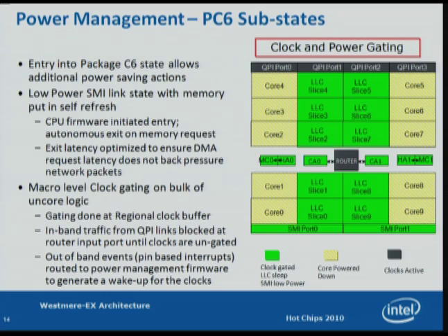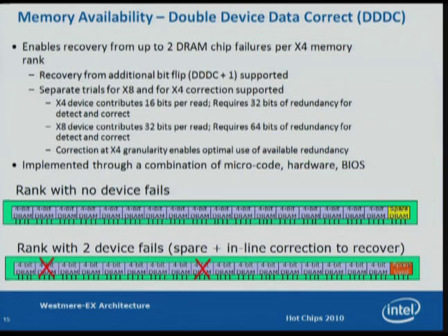There are some areas like the router that are still running clocks freely, because that is where all of the in-band traffic gets buffered before the clocks wake up, right? And if you have out-of-band wake-up events like a pin-based interrupt, that again is transferred to our power management firmware, which wakes up the clocks. Okay.